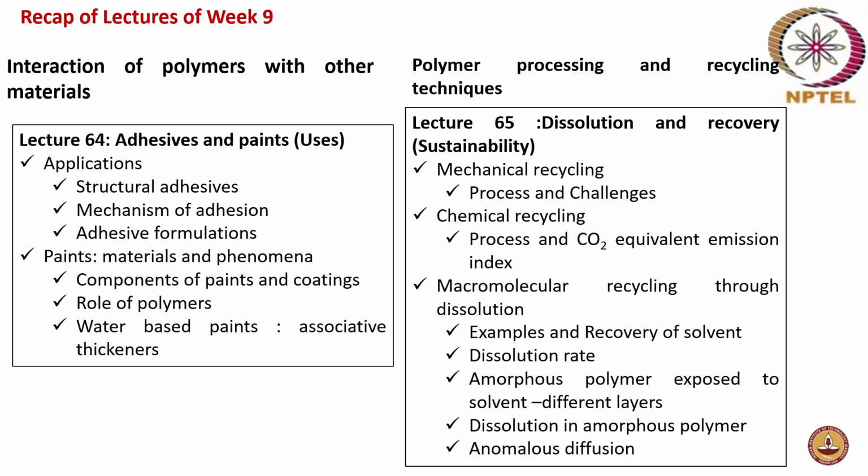Now you have to take it back so that you get the pure polymer. For that you may use some anti-solvents, right? And again, when you are using a solvent, there is an sustainability aspect, right? What about the recovery of solvent, or you are using some organic solvents? For example, when you want to recover HDPE or LDPE or polypropylene, some of the common solvents used are toluene, acetone, xylene, and hexane. So these are all organic solvents. Again, when you are having organic solvents, they'll have environmental impact, like they may be carcinogenic. So this is again a point of concern.